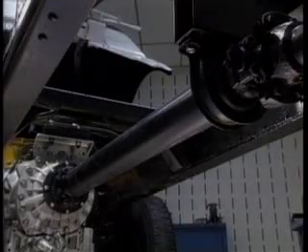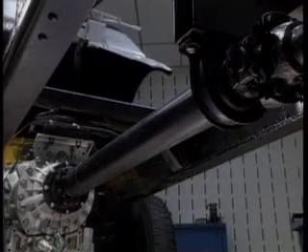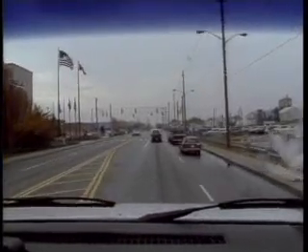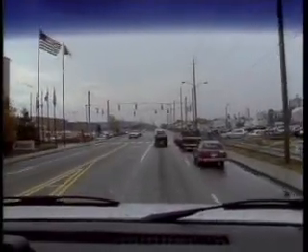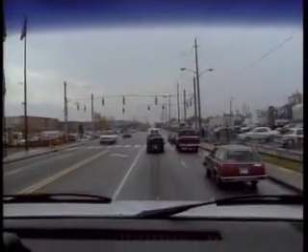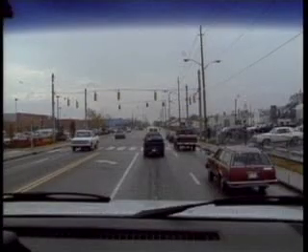If torsional acceleration is beyond specified limits, vibrations can occur. Sometimes these vibrations can be felt by the vehicle operator, and other times they can't. Even though the vibrations aren't felt, they can still cause transmission or axle damage. That's why the software's calculations are so important. Trouble may exist without drivability problems.